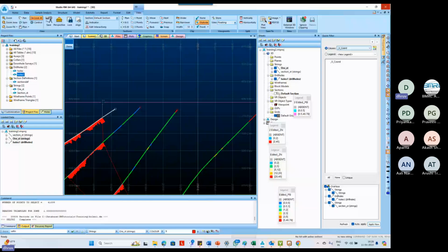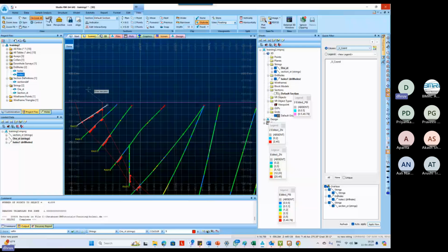Then the final close, when you have to close it, so always you have to close the string for creating a wireframe of closed volume. So you can't go and snap it here. You have to, on keyboard, type CLO, which is close string, the command, you can see at the bottom right corner, CLO is close string. So now the string is closed. If you verify the string by clicking it and checking it with QST, you will see that it is mentioned at the command output prompt. In this view, the vertex order is anti-clockwise, and this string is closed.